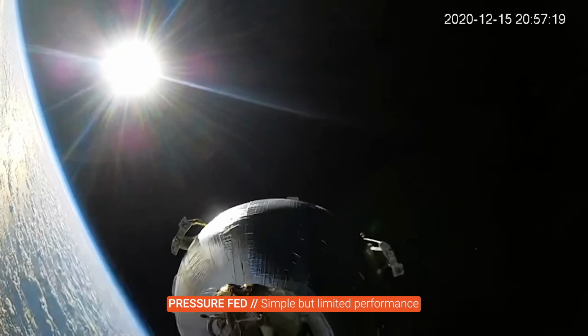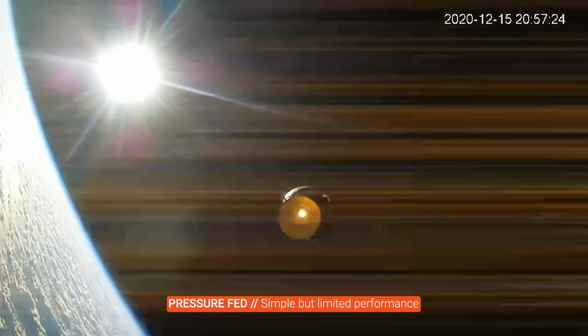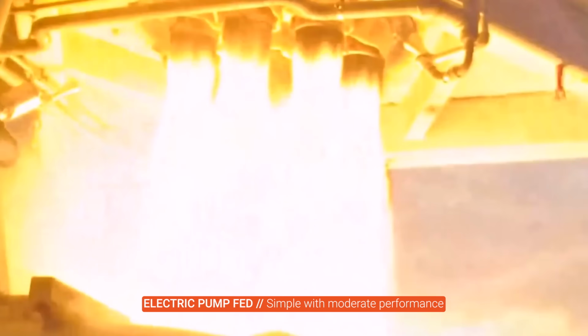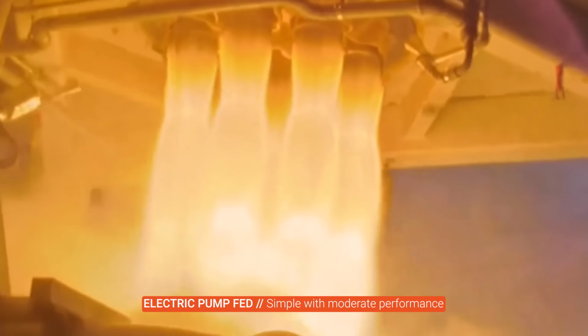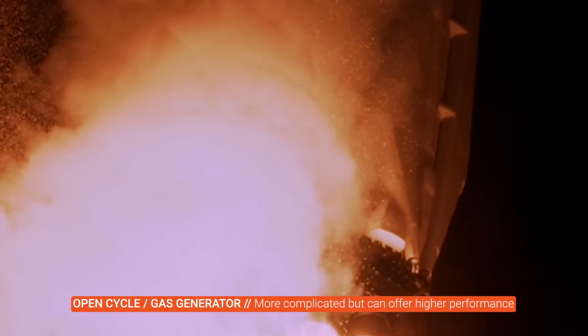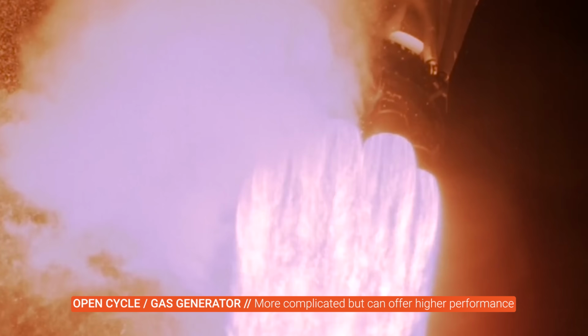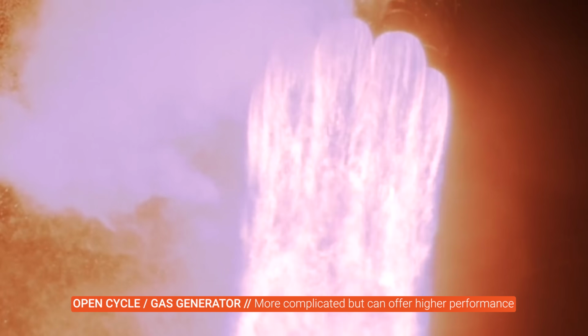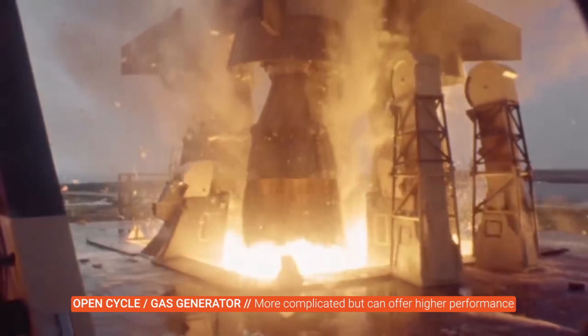There's definitely the elegance and ease of pressure-fed engines, but their performance is limited. Meanwhile, the electric pump-fed cycle is seeing a new rise in popularity with the increased density of lithium-based batteries and more advanced material science. The gas generator cycle is still one of the most common cycle types, and it blends a very healthy amount of performance and relative simplicity. It seems to be a great all-around compromise.